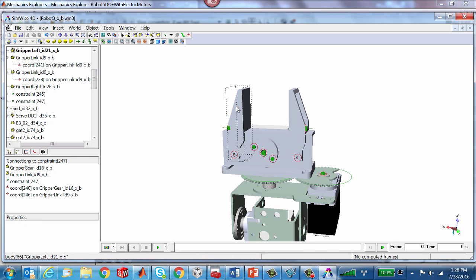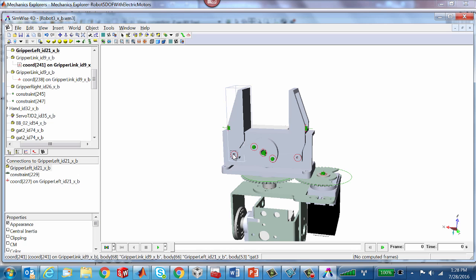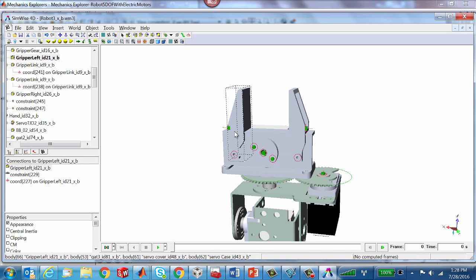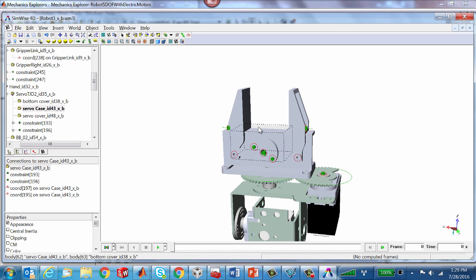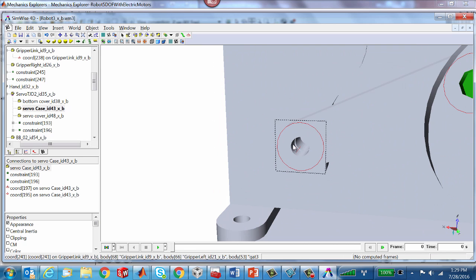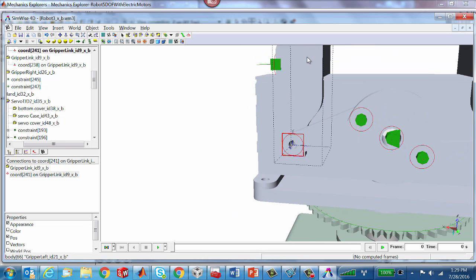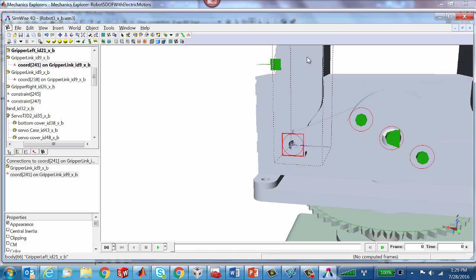Okay, and what I'm going to get at is an issue when you have closed mechanical linkages. And the basic idea is that this crank is connected to this piece, that then connects to this link, connects to this piece, which then is connected to this piece again. Okay, and for various reasons, you want to be a little bit careful, and you generally like to impose as minimal a constraint as possible. All right, and so what I'm going to do is I'm going to select that. Let's move back here, and you'll see I'll select the little slider, the little gripper.